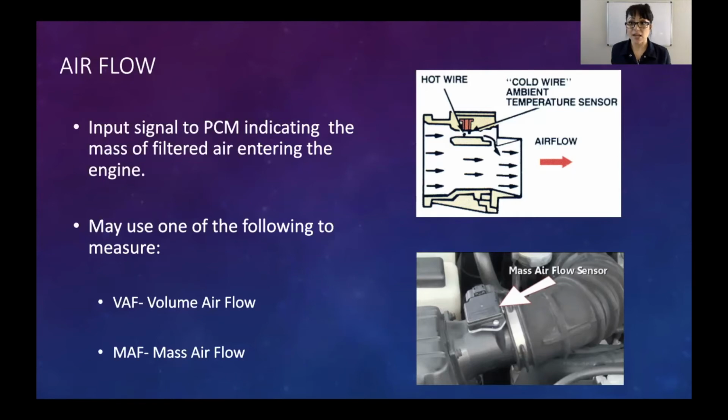Depending on how well it cools down, this hot wire is going to determine the temperature, which also gives us air density. So if I've got a 1 foot by 1 foot box that is sealed, and I have 100-degree air, versus the same box that has 60-degree air, there's going to be more oxygen in the 60-degree air box, which means if that air is going into the engine, it requires more fuel than the box of 100-degree air, if that makes sense. So we don't use volume airflow sensors very much anymore for that reason. Mass airflow sensors give us more information.